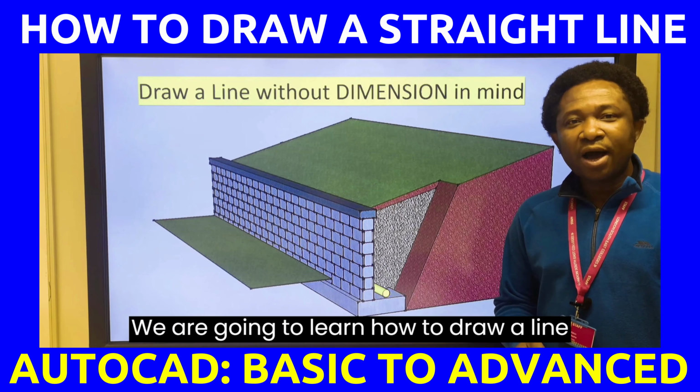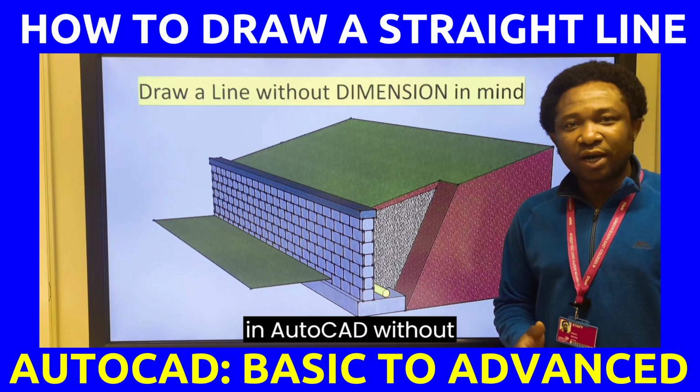We're going to learn how to draw a line in AutoCAD without dimension in mind. Let's assume we want to draw a straight line to represent this wall. The first step is to pick a line command. The second step is to click the starting point.